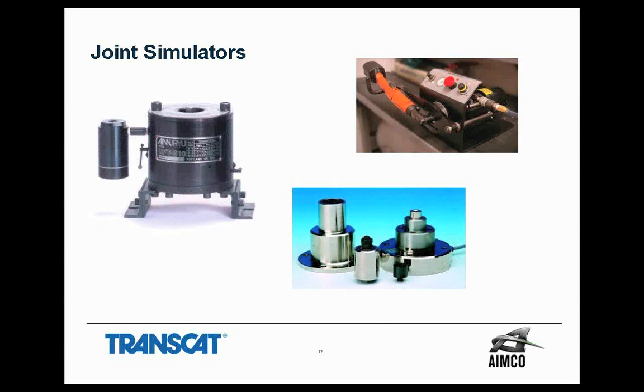You can get simple mechanical Belleville linear joint simulators that run from $500 to $2,000. You can do a hydraulic accumulator with flat coil springs and Bellevilles, which runs $5,000 to $15,000. A lot of customers use brakes because they don't have to be reversed. All they have to do is be released. Brakes aren't really linear, particularly at the harder joint rates, 30 to 100 degrees. They do not have a linear response, but they provide the benefit of not having to be reversed.